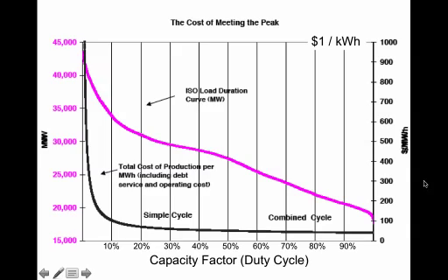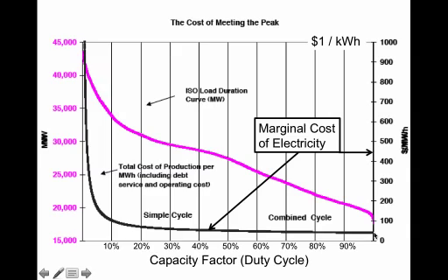We see that the cost is in dollars per megawatt hour. So you can take this number and divide by 10 and you get cents per kilowatt hour. And so we see that the facilities we use all the time cost about 4 cents a kilowatt hour. This is called the marginal cost of electricity. This is the cost of the last facility that you dispatched.